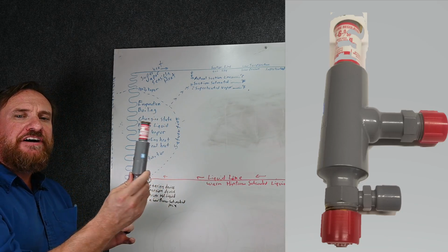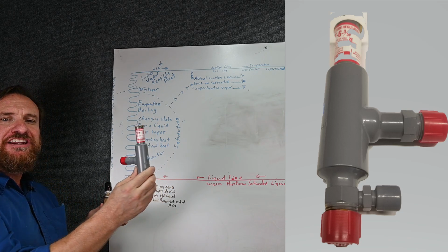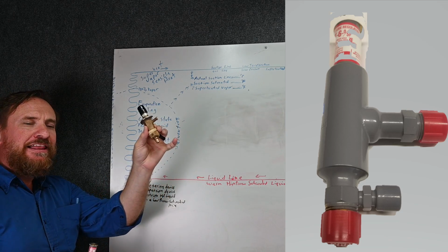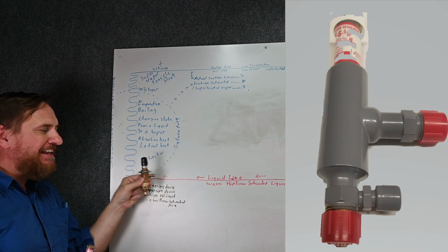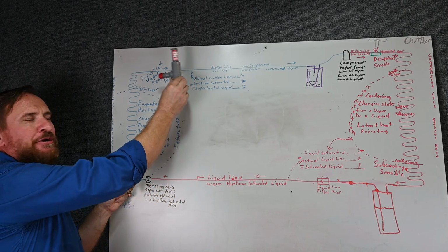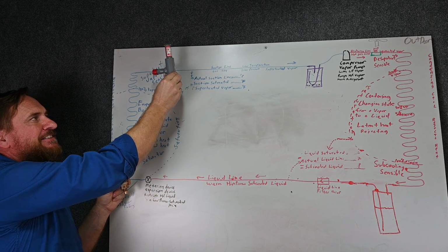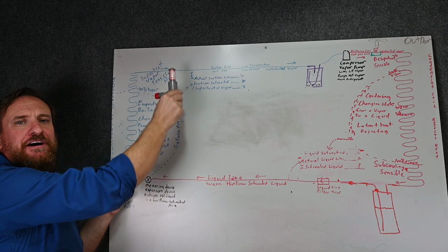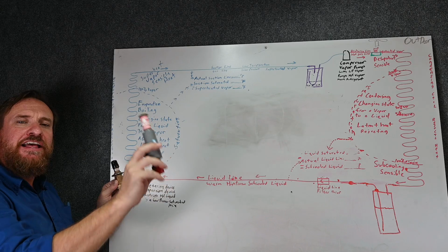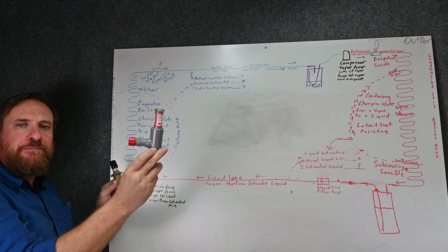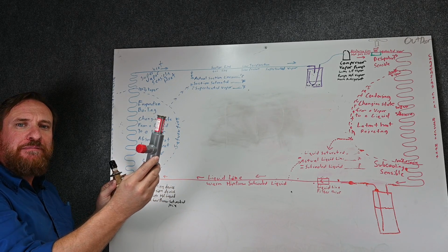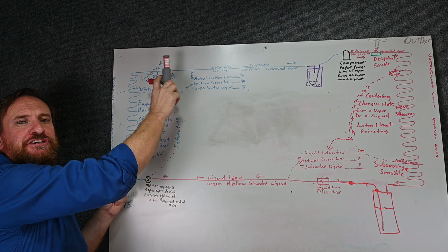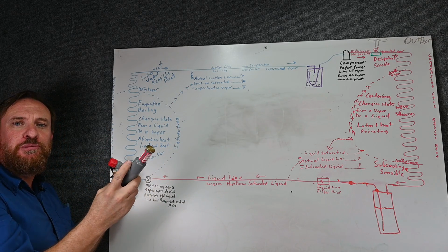There is another device that helps control suction pressure called an evaporator pressure regulator. A lot of times people will get these mixed up. The automatic expansion valve is a metering device. An evaporator pressure regulator is a device that goes in the suction line that helps build suction pressure. It keeps a minimum suction pressure of X, Y, and Z. This is also going to be a commercial component, typically with multiple evaporators. You put this on the higher temperature of the evaporators, and it keeps the suction pressure high enough into a range for its normal operating.